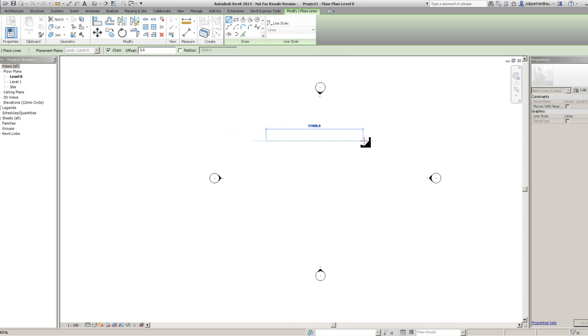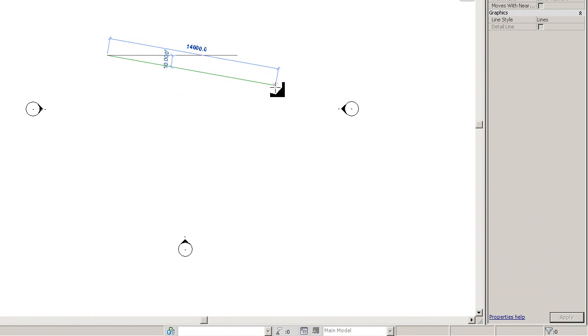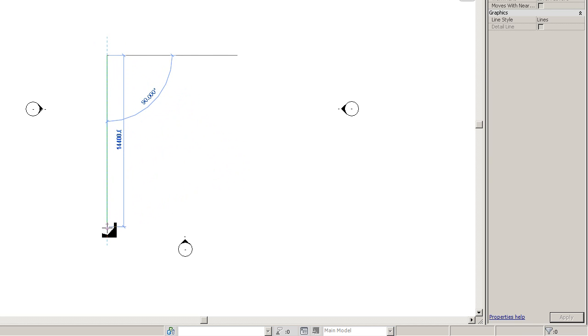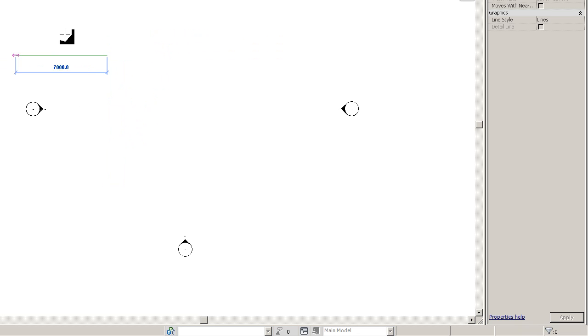So I'm going to bring my mouse across, and you can see it's snapping to the horizontal on there. Okay, we don't have an ortho mode or polar mode or anything like this, but it does keep it quite nice. If I snap to say the closest 45 degrees and 90 degrees, you see how it snaps to it. What we can also do, for those who are sticklers for drawing right angles and vertical and horizontal lines, if I hold in the shift button as I move my mouse around, it will actually lock it in to those. So those of you that really feel like you need to do that, we can simply do that. Just for now though, I'm going to keep it a little bit more freeform.